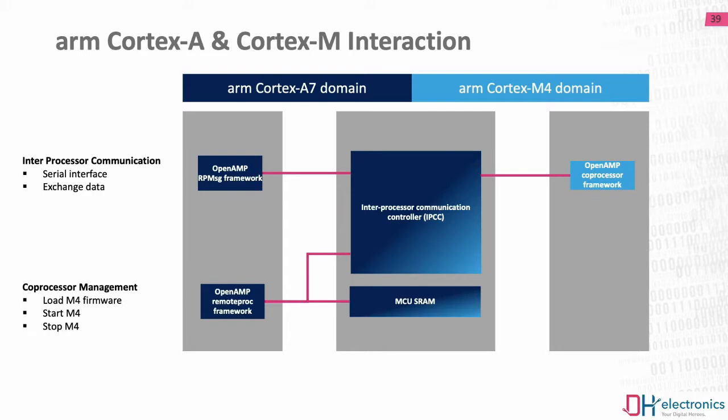Next to this, we have on the Linux side the OpenAMP remoteproc framework, which can be used for lifecycle management. This means remoteproc can load the M4 firmware and can start or stop the M4 coprocessor.